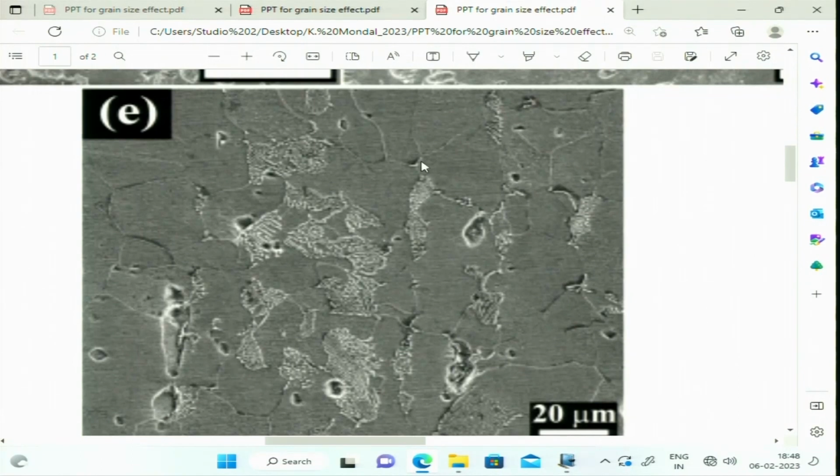So, these are actually forming along the ferrite grain interface, that means grain boundary, ferrite grain boundary, whereas if you consider this particular one, you follow the cursor, here it is falling at the pearlite ferrite interface. So, that means the pearlite colony and ferrite grain interface is forming. For example, here the 3 pits are actually along the ferrite grain. So, every time we are seeing some of the pits, they are actually forming along the grain boundaries, whether it is an interface between pearlite colony and ferrite grain or between ferrite and ferrite grain.